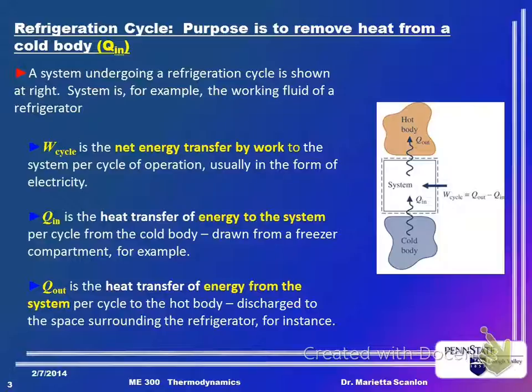So what is the sign of W cycle for a power cycle versus a refrigeration cycle? It's the opposite. Refrigeration will be negative because it's work done on the system. Power cycle, W will be positive because it's work done by the system.